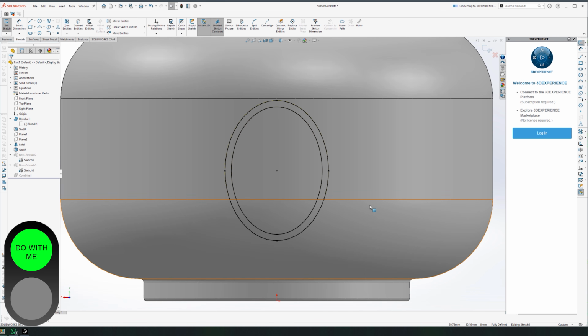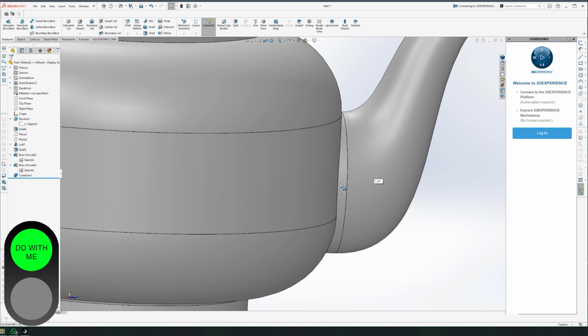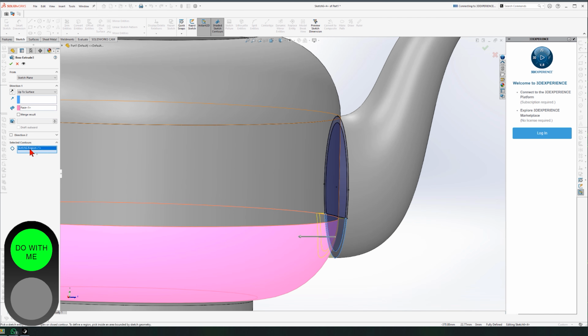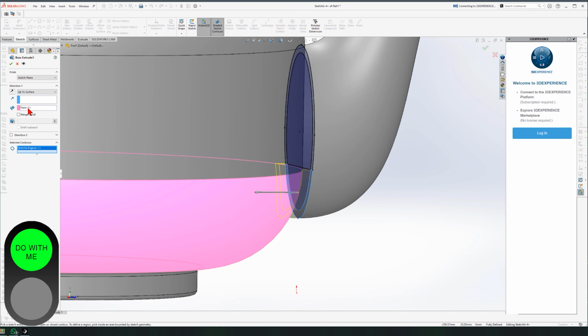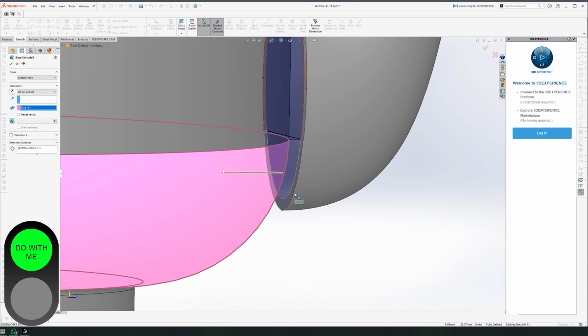So I had to split them, and when I split my area, I got the error. You saw that. So I deleted what I had and I redrew everything. So the first upper half is this. I'm selecting my upper half, or this is the lower half in this case, my lower half in the selected contour section here. And I'm selecting this pink area as a reference where this lower half is going to be extruded until or to.